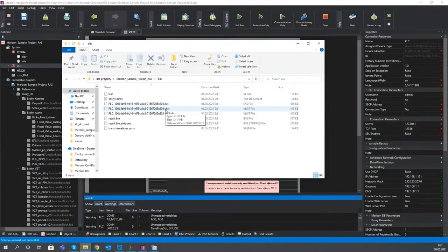Their file extensions are Vlist. So you can see one of them here and another one here. The Vlist is short for variable list, and the name of the PLC is here. Here in the project you can see the PLC name, which is PLC with not much fantasy, and the same text string is here. The difference between those two files is just the coding of characters. So normally it doesn't matter if you use just Vlist or the UTF-8 Vlist.